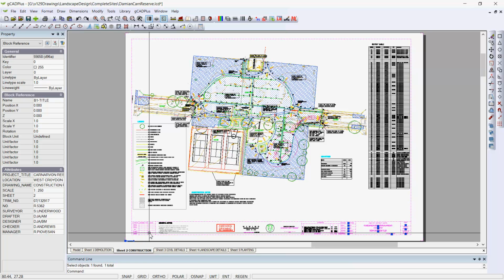The height of text and information that you put in that text is often dictated by the drafting standard that you are working to. Most countries have a drafting standard and will specify what goes on a sheet such as this. We're operating here in layout space, so our text heights and line thicknesses and so on need to be set appropriately for the size sheet.